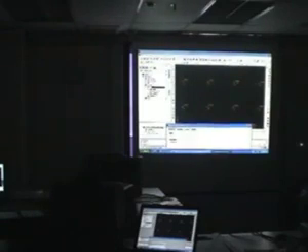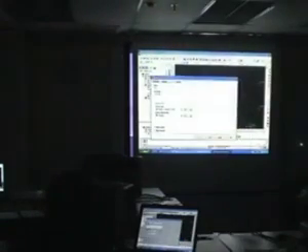You don't have to erase them or switch out the layers, none of that. You just need to play around with surface styles. And you can create your own surface styles if you want to be very specific. Instead of a 1 meter interval for contours, you can set 5 meter intervals, set different colors, and different layer names for the contours. Everything is completely customizable in Civil 3D.